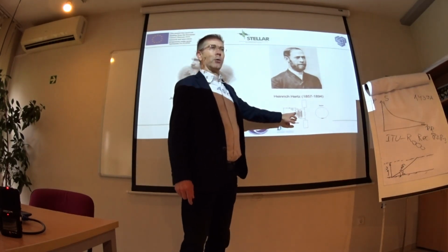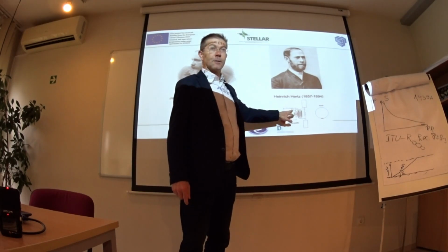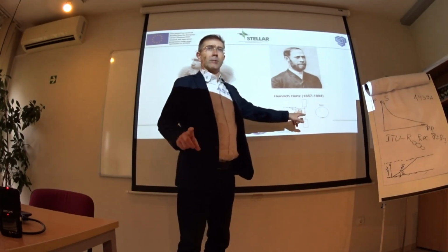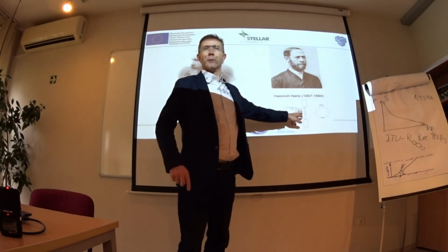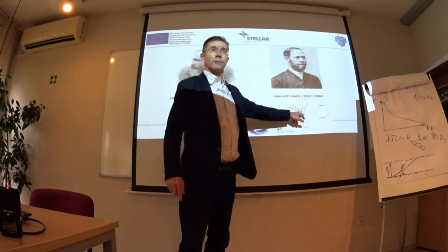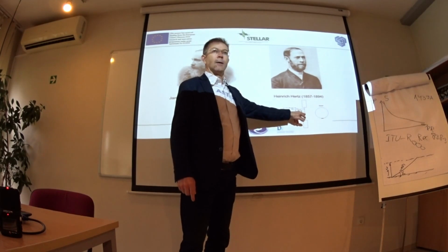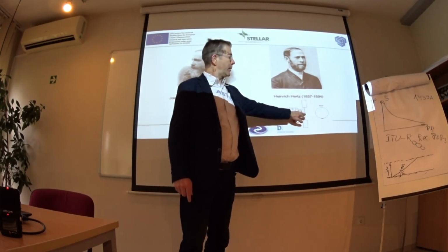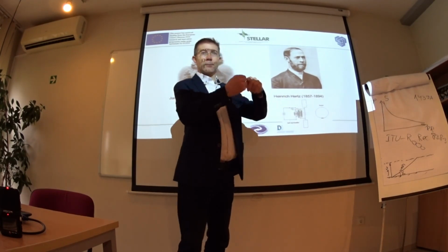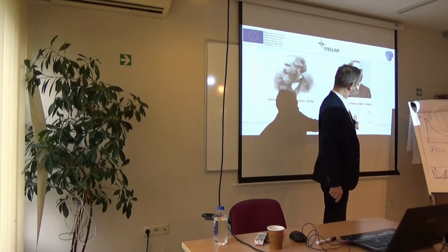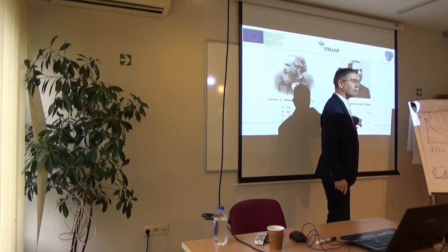So high current, low voltage in this circuit is transformed to low current, high voltage oscillations in this circuit. And because the voltage is high, a spark happens between these two spheres.